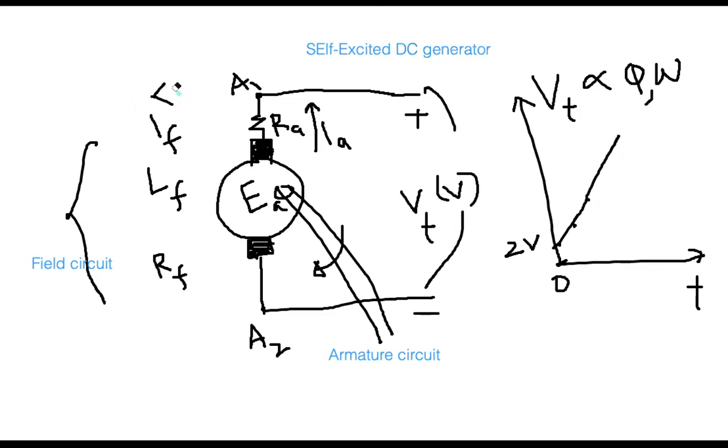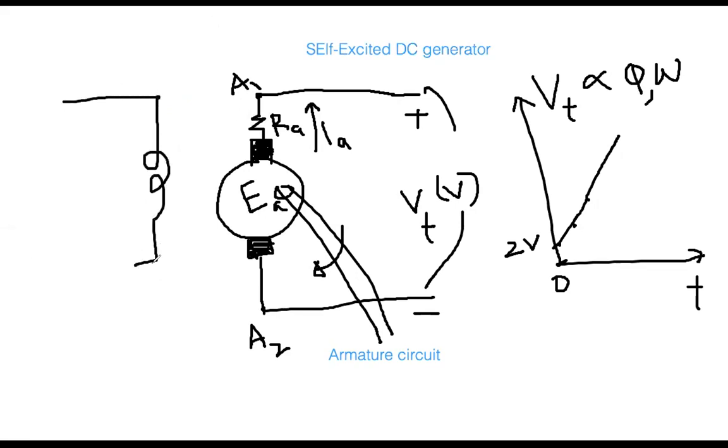You first disconnect this one from these two terminals, and then, as I'm showing, you connect it to a DC source. You apply some DC volt for a moment, making sure that current is flowing to that field coil. Just for a few seconds, you turn on this DC voltage switch, and this is called field flushing. If you remember my previous slide, it is called field flushing.